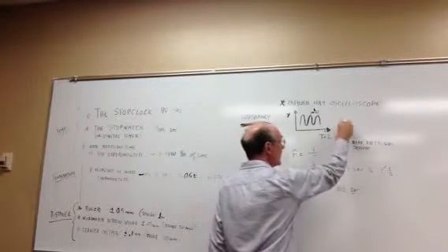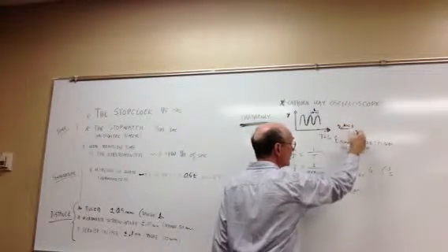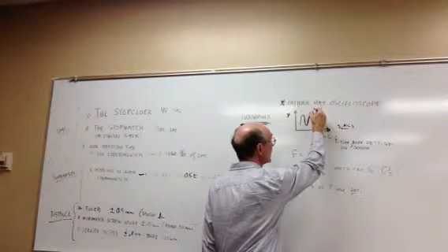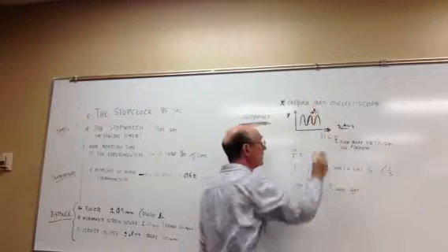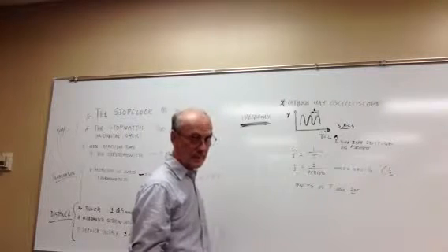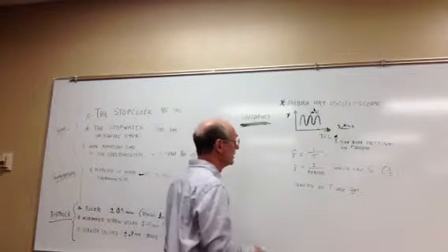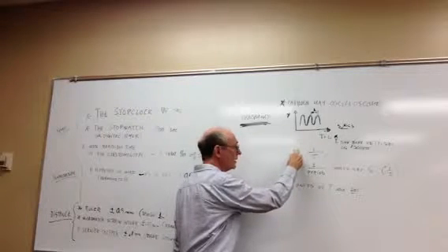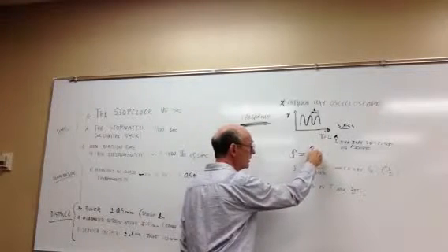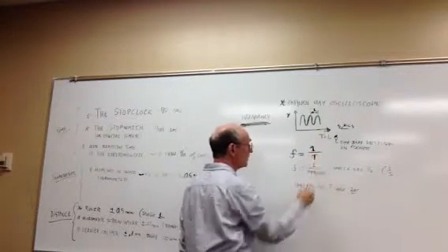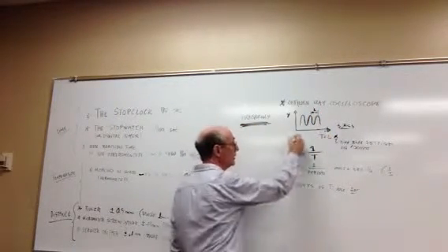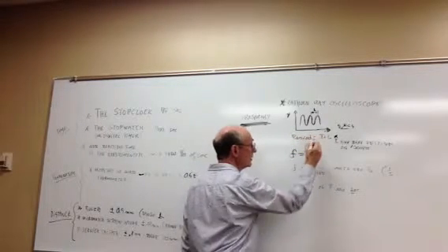And depending on the time-base setting on the oscilloscope, the time corresponding to going from here to there is L times the setting on the scope. Then the frequency would be given by 1 divided by the time, the period. This particular time is called the period of the signal.